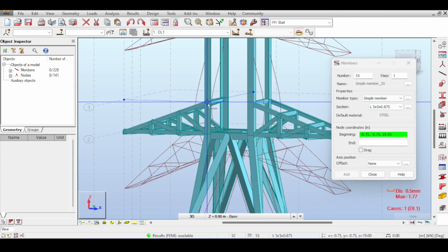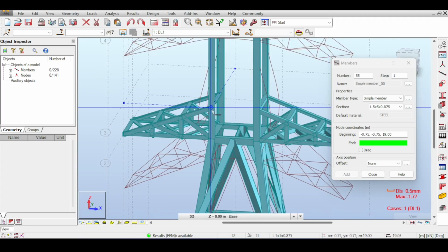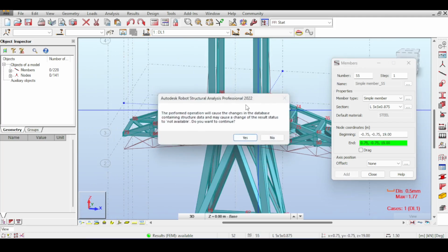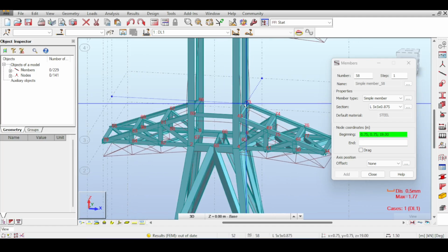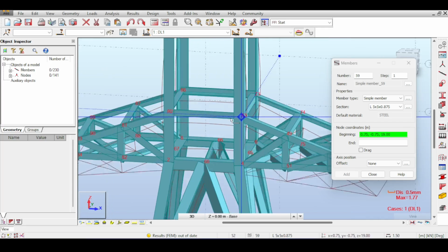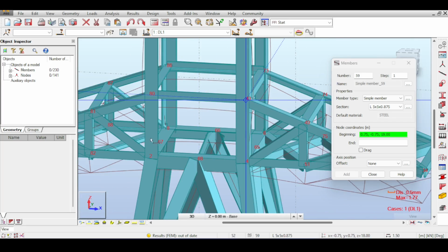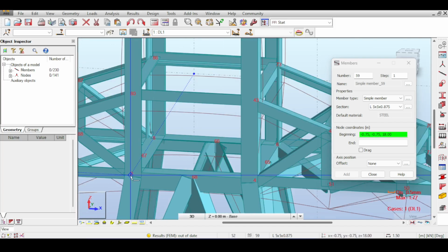I think that if you basically draw this, let me show you. If you draw this from here, now I need to open the nodal numbers because I want to make sure I'm clicking correctly. To here, so that's one element, and well, here, second element. So I was thinking instead of doing this W-shaped system, you can just make a simple bracing. Now tell me in the comment section what you think about this. I think this would be much more sensible because the tower is now smaller. However, I want to keep the general shape of the tower, so I'll just do it by hand.